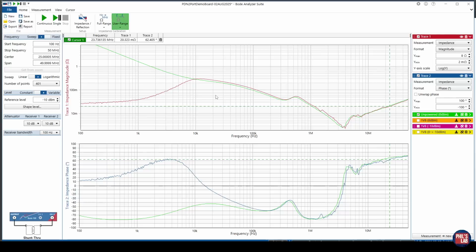The measurement shouldn't change. In any case, now we can see various different characteristic behaviors. At low frequencies up to this cutoff frequency, LDO, our regulator with its control loop, dominates the impedance profile. And it seems like if we take the cursor, move to the far left, our low frequency, so around 100 Hz, impedance is about 26 milliohms. As we go higher in frequency, 1 kilohertz, or we reach our peak at 10 kilohertz-ish, we get up to an impedance of about 300 milliohms, so 0.3 ohms.